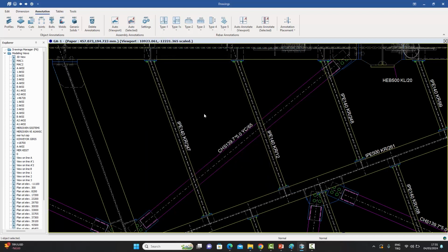And how do you use it? This one already has the existing annotation, so I'm just going to select this frame and say annotate the selected profiles. And now it has annotated it with the new one. This new one was what I just showed you. It's custom based. You probably made a bracket, then wrote a P, then put a dividing sign, then the number, and then the bracket again, and the second line material. You could have made different sizes, different colors, whatever you want.